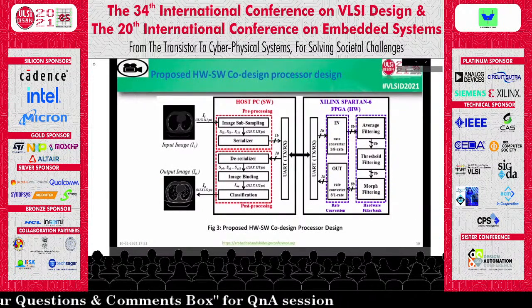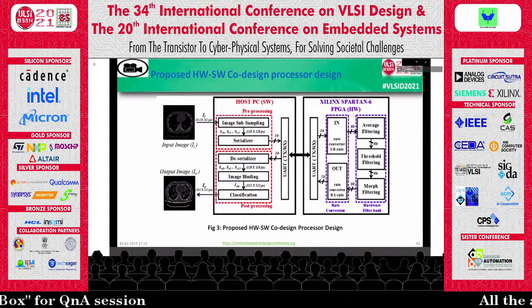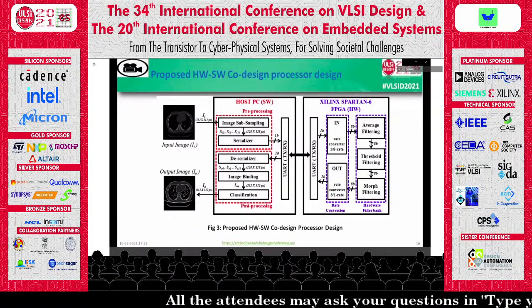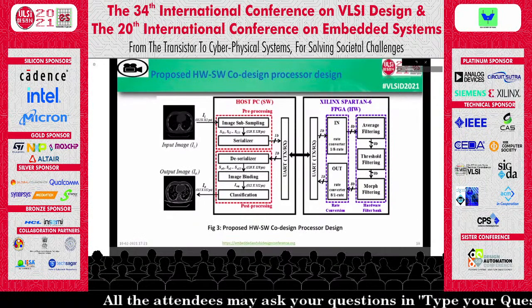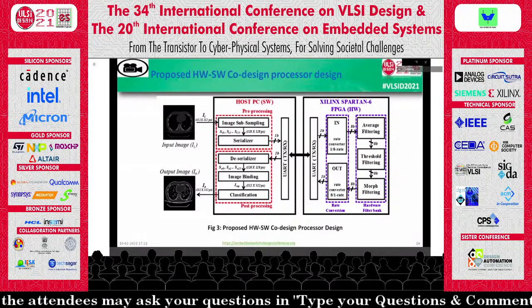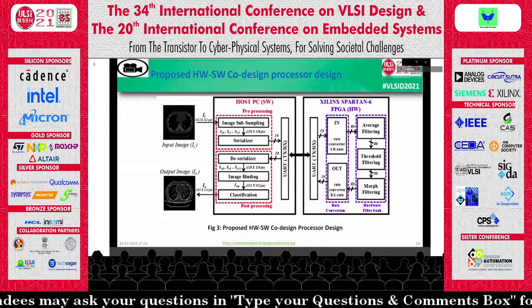Boundaries of these smaller samples are padded with zeros in order to reduce the boundary condition error in averaging and erosion filtering techniques. Later, the serialization block is used to convert the two-dimensional image to a one-dimensional signal, where a 2D image matrix is converted row by row to a one-dimensional signal and sampled accordingly.